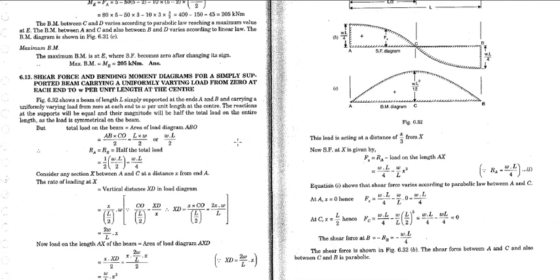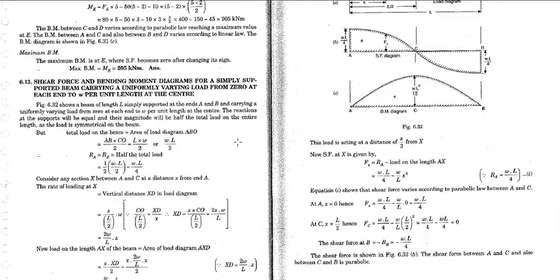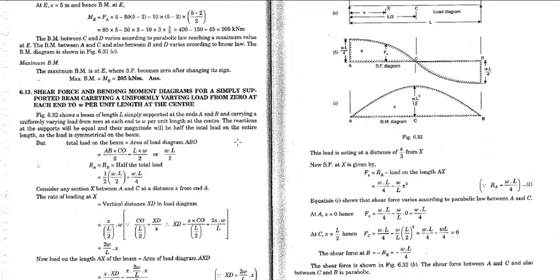The same thing we have to use over here. We convert this area into a point load, take the CG, and then calculate these values, and the convention will be based on what I have just taught. By this way we wind up this session for the SFD and BMD for the simply supported beam, and in the next video we will see the SFD and BMD of different types of beam. Thank you.